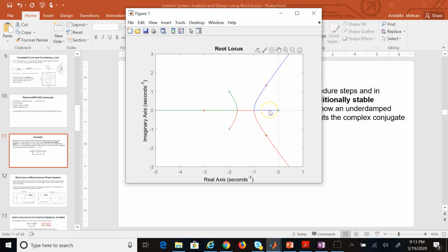But if I change k, let's say bring k all the way to this 20, even if I make it very close to 20, 19 point something, where are the poles? So one of them is here, one of them is here, and one of them is probably somewhere there, right? And this term is always a negative exponential, so that term would go away completely, and that is a decaying exponential.